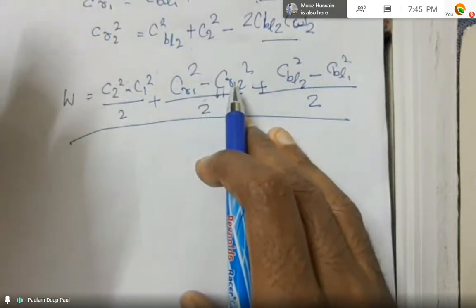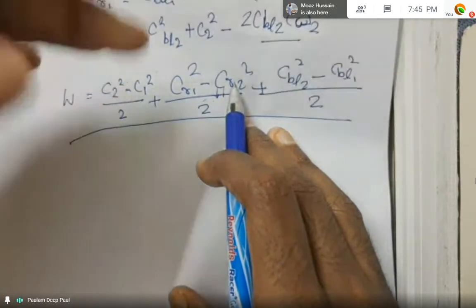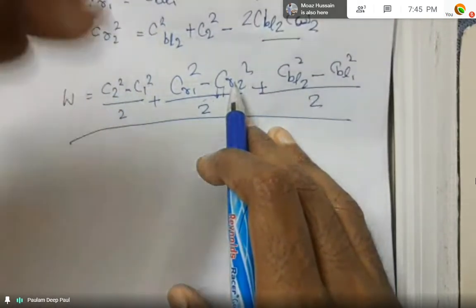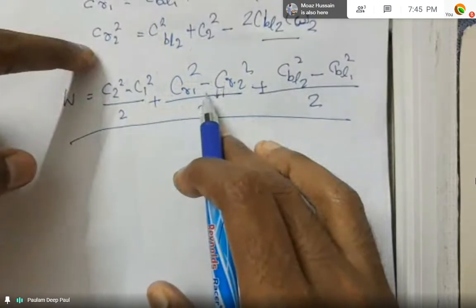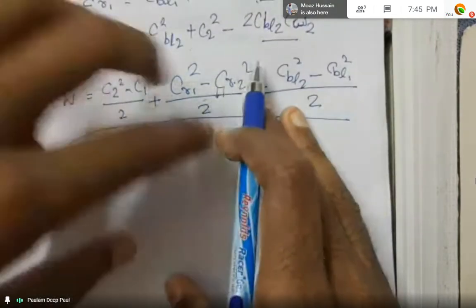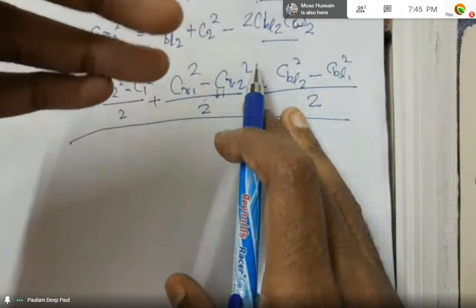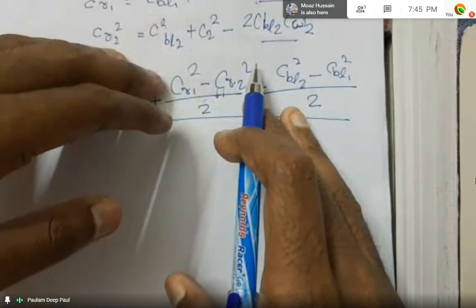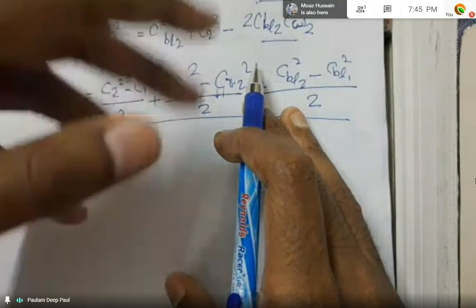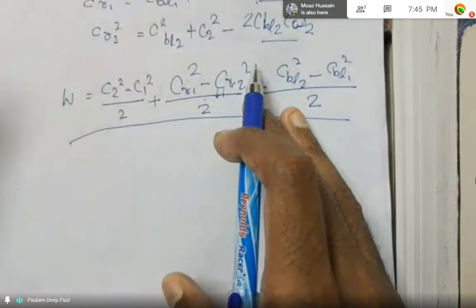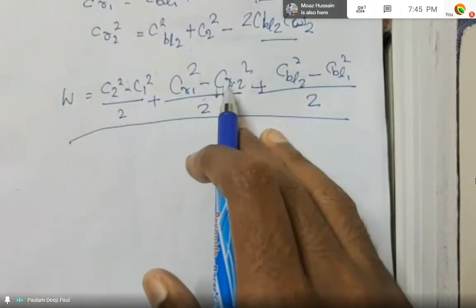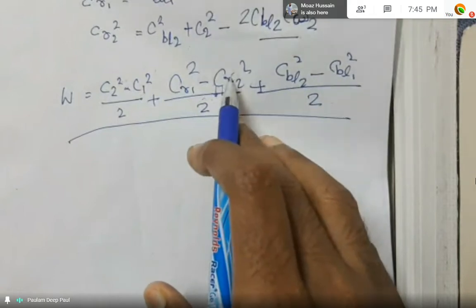So due to the diffusion, as the air is passing from the impeller to the diffuser, the relative velocity decreases, and hence we can see a relative velocity. I mean, the velocity of the incoming air, or any incoming fluid, with respect to the blade velocity, that is the relative velocity, decreases due to the diffusion action.